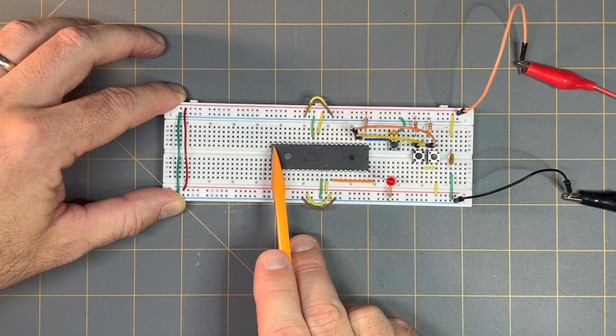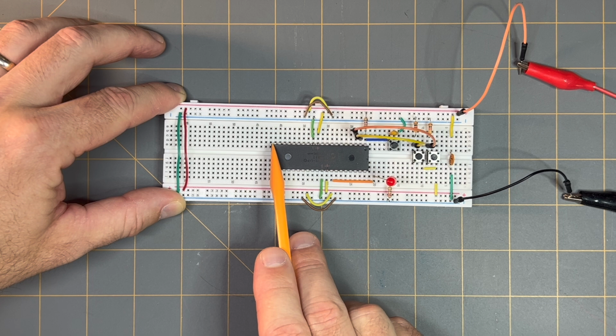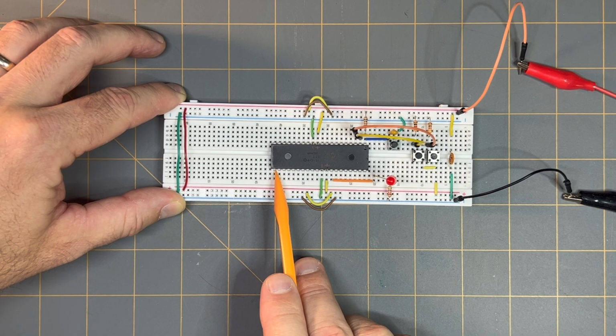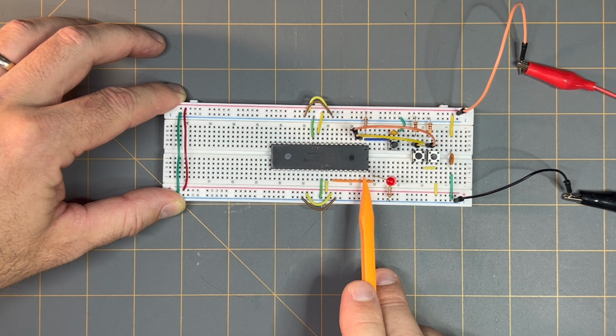Pin 20, which is the lower pin on this side of the PIC microcontroller, is in point D41 on the breadboard. Pin 21 of the PIC microcontroller is at point H41, and then pin 40 of the microcontroller is at point H22.